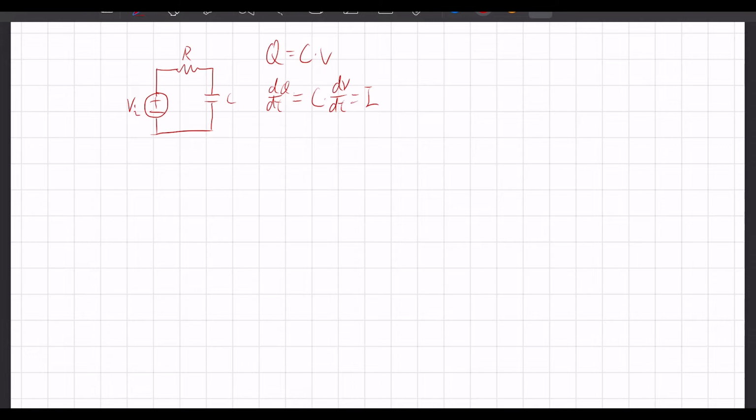To calculate the time in the circuit, we need a conversion in the circuit before it can be used. Our group used resistor and capacitance integrator to convert the output into ramp signal waveform. First, we need to derive the square wave of the circuit using KCL, Kirchhoff current law, to get the following formula.